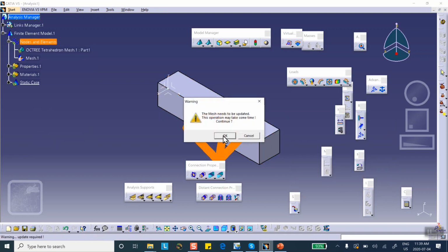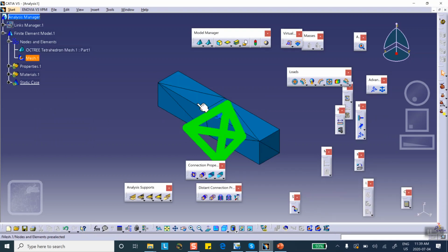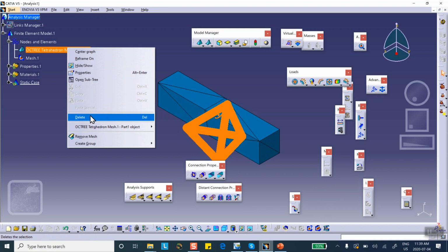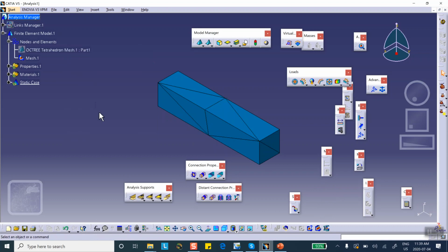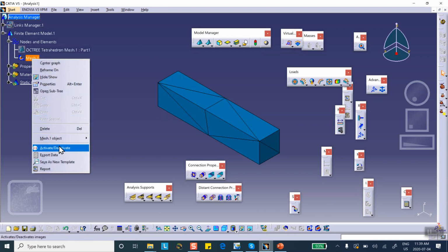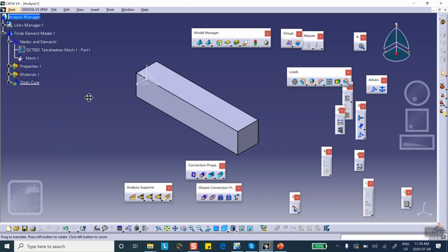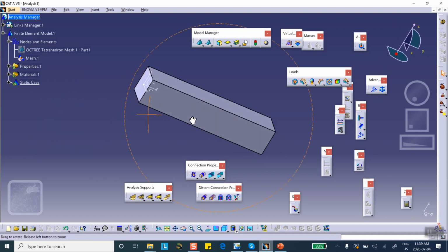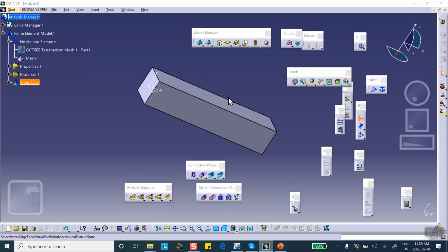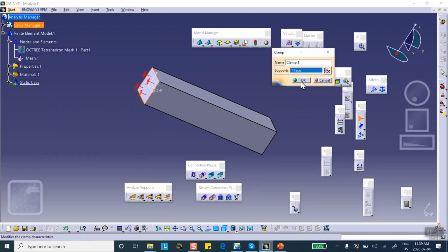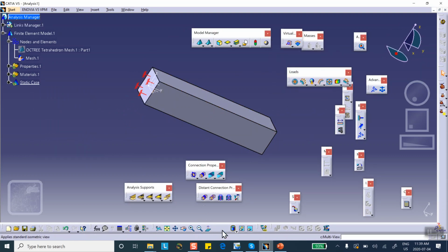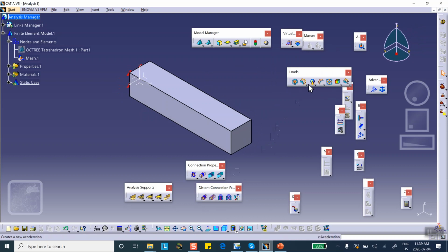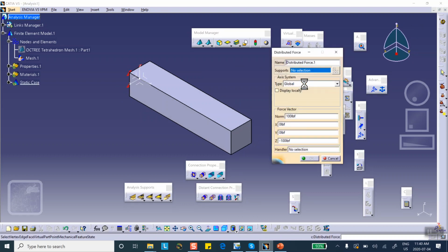So anyway, mesh visualization right here. Okay, very coarse mesh. And now I'm going to hide this generic element that we have here. Hide it. Okay, good. Now, deactivate the mesh. So there is my part. We're going to clamp the left side, so clamp the entire face. Okay. And on the right side, I will apply a force, total distributed force of 100 downward.